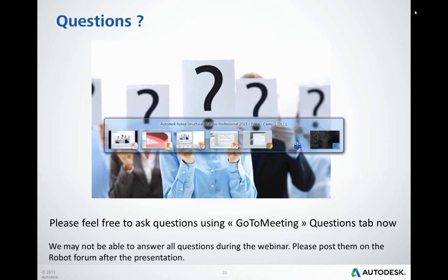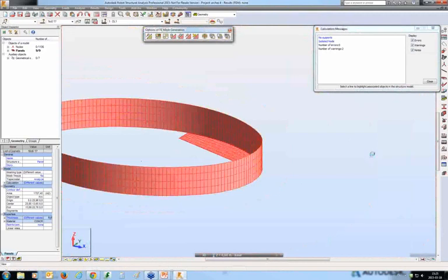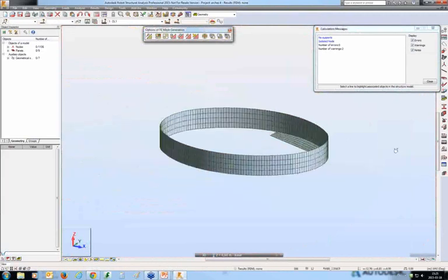So Artur, we have a few questions that were already answered by Francois and Rafael, so thank you for doing that, guys. And then we have some coming in. So one here, you can let me know if this applies or not. When I have a pile cap consisting of a plate connected to piles by single nodes, what is the best way for meshing to get realistic sectional forces to design the plate rather than having very high concentrated results on the connecting nodes?